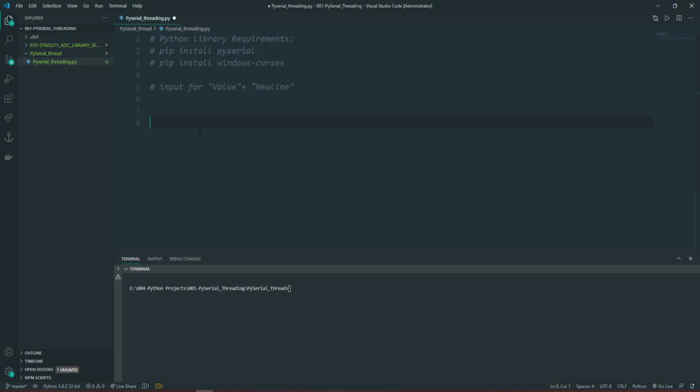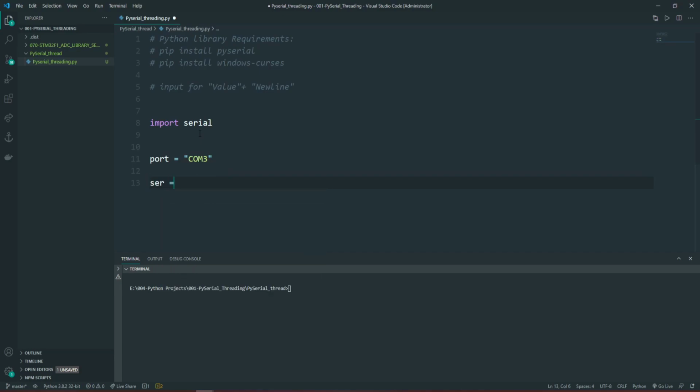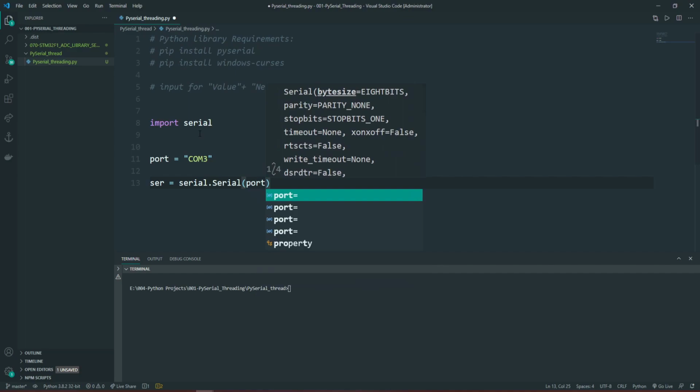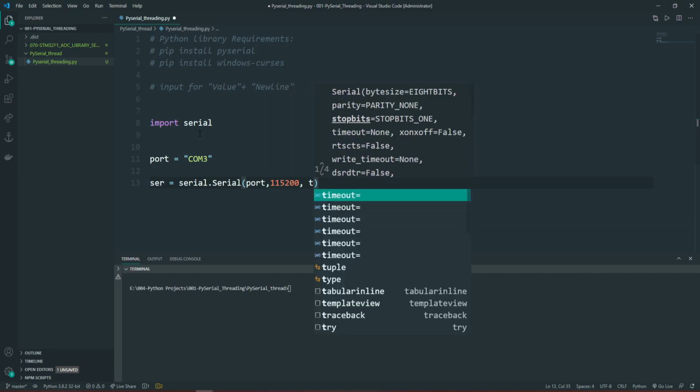After that you just have to import serial, and that's all. So the magic is quite easy to make. Port, I will call it COM3, so it would be called port. Do not use a magic number. And then let's have a ser, the serial connection that we are going to use. It will be serial.Serial, and the port I'm using is COM number 3. The baud rate at the end of my microcontroller is 115,200, and I will use a timeout equal to 0.